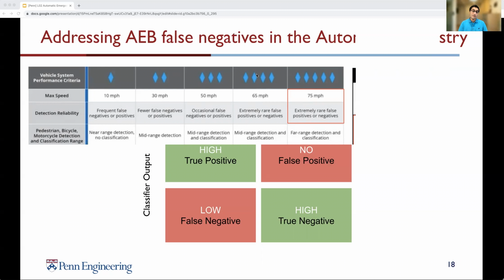And also it has dynamic driving capability where it can intervene and do this collision avoidance by maneuvering both longitudinally and laterally away from the accident and the risk scenario. Right, so for example, they come up with labels on the right-hand side, which show, okay, this particular vehicle has a 2.4 star rating for automatic emergency braking. That means that up to a max speed of 40 miles per hour, AEB will work fine, and it also has some moderate amounts of false positives and false negatives.